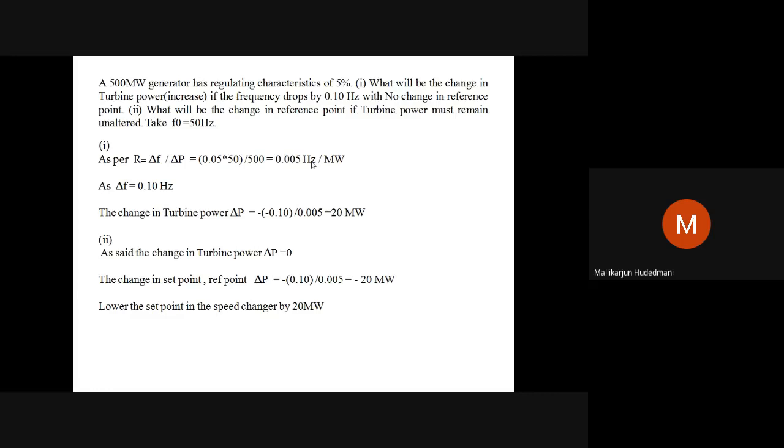Definitely, because I am working on AGC, ALFC, automatic load frequency control concepts, where there is a change in load and frequency gets affected. To address the frequency, I have to supplement megawatts. In that respect, change in frequency and change in power is my need. Hence, the units are converted to hertz per megawatt. We have not done the same thing in the basic introduction model.